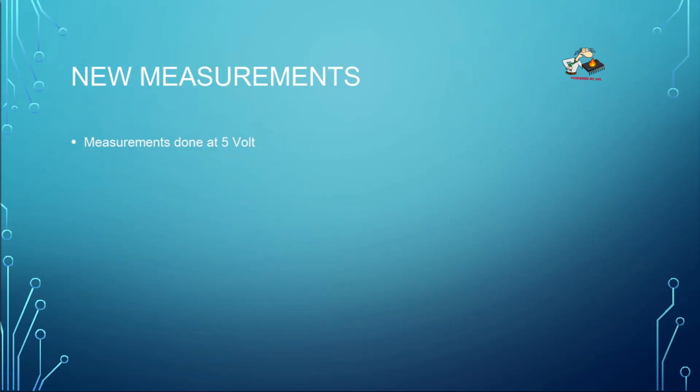So, new measurements. They were done at 5 volts because I'm using 4 AA rechargeable batteries, so there's more or less 5 volts. When inactive, the device consumes only 25 microamps. And when active, it consumes around 50 milliamps.